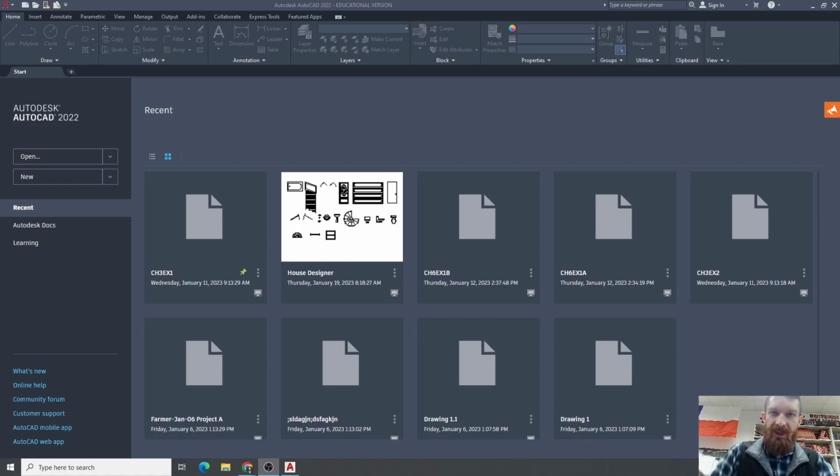Today we're going over Chapter 12 of AutoCAD. Chapter 12 is all about advanced drawing setup. So our objectives today, number one, know the steps for setting up a drawing. Number two, be able to determine the appropriate limits. Number three, be able to calculate and apply the drawing scale factor, or DSF. Number four, be able to access existing and create new template drawings. Number five, know what setup steps can be considered for creating template drawings. So let's dive right in here.